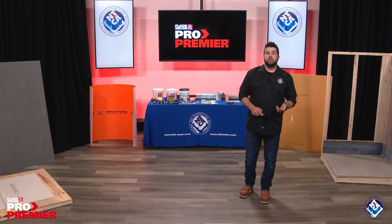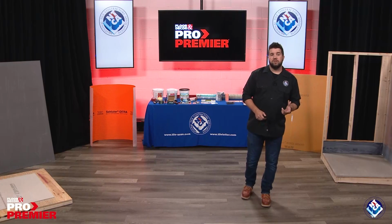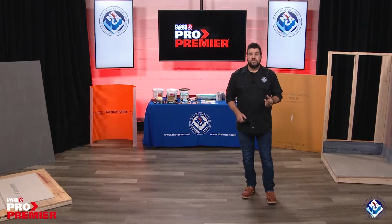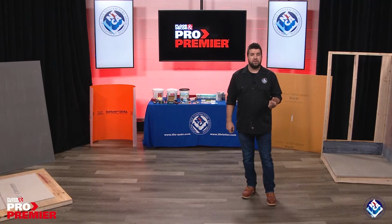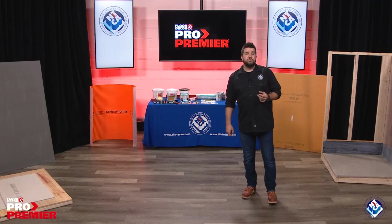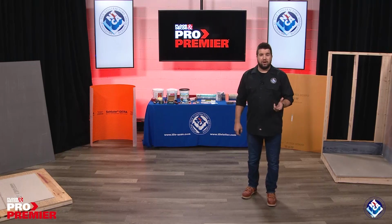Let's start off by taking a look at backer boards. There are 6 different types of backer boards listed in the TCNA handbook. As we look at some of these details, you will notice that some of them have a designated ANSI standard and others have an ASTM standard. This is just the difference between how the manufacturer structures the testing for their product and which entity was used in the testing. When looking at a TCNA handbook detail, you'll find sections called recommended uses and another section called limitations for each category of backer board.